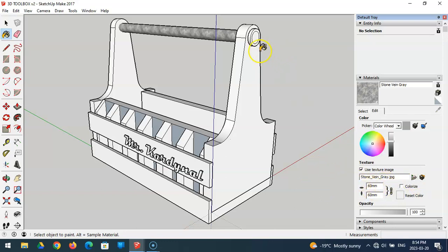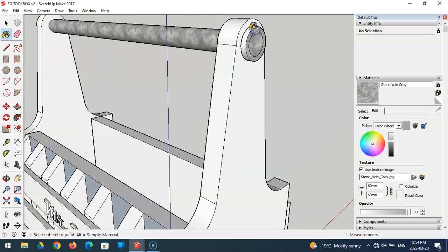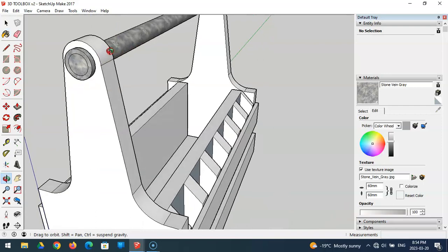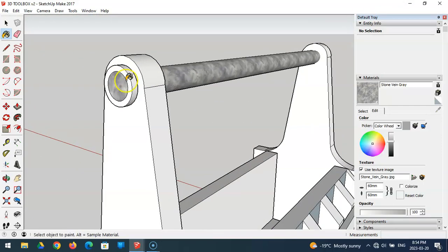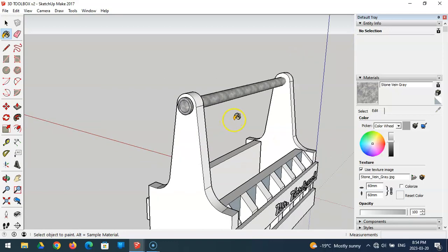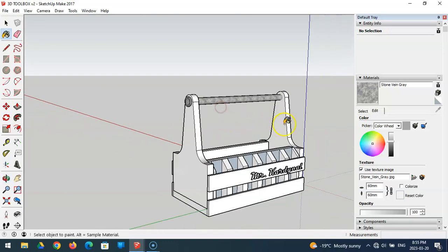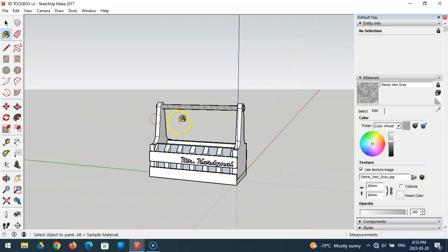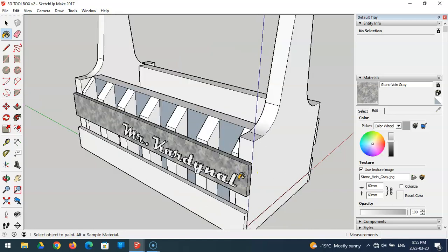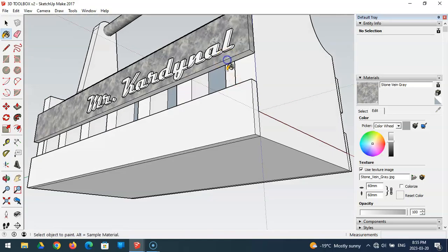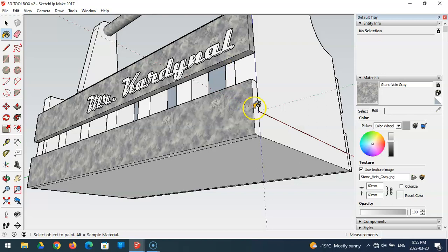And that's stone, so I'm going to just cap these with stone as well, if it lets me. You might have to zoom in at times. And you just point the end of your paint bucket on the different pieces, just like that. Okay, I like that. Now because that's stone and I want some things matching, I'm going to do the same. This is going to be stone, and you'll see that you have to do every single face when the item is not grouped.